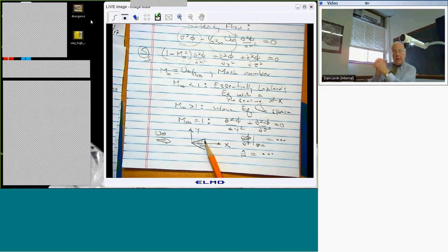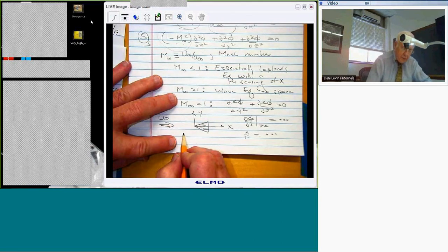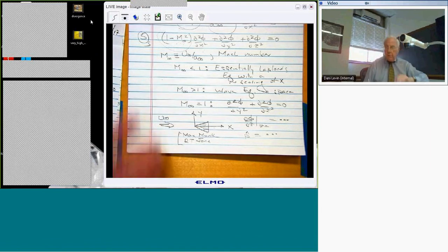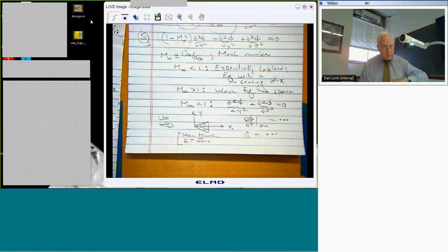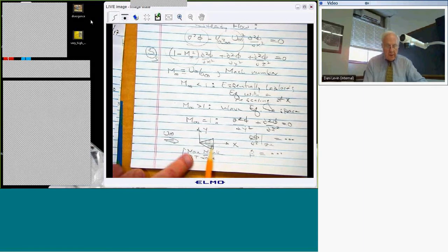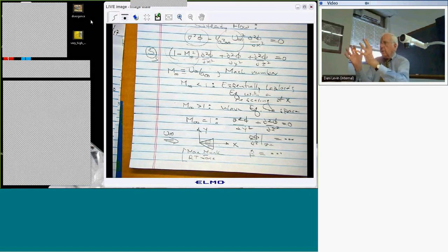And this is called slender body theory or slender wing theory. And it was very controversial for a long time because people thought that, gee, that can't be right. But a couple of very smart people proved it was. One was Max Monk, and the other was R.T. Jones. And there are other people who worked on this over the years. So if you have a very low aspect ratio wing, you have something where the span is small compared to the chord, this actually gives you fairly sensible results.